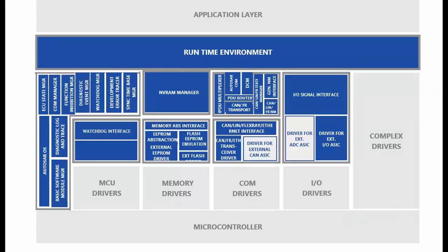See, this diagram belongs to BSW modules. Here we have DCM, Diagnostic Communication Manager, then NVRAM Manager, and these are system services. This whole thing belongs to the basic software module. In this we also have complex drivers, microcontroller, then MCAL, the microcontroller abstraction layer, ECU abstraction layer, runtime environment, and application layer.